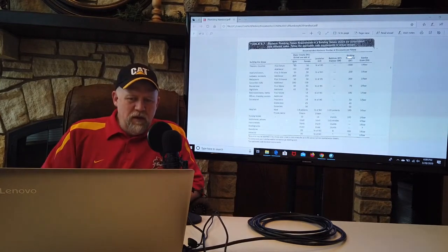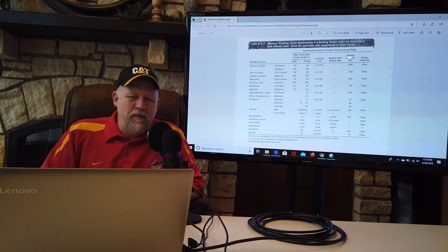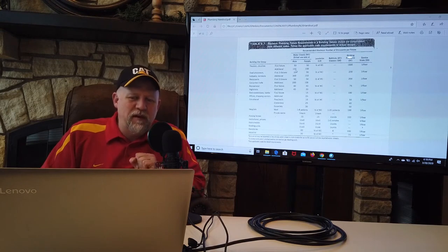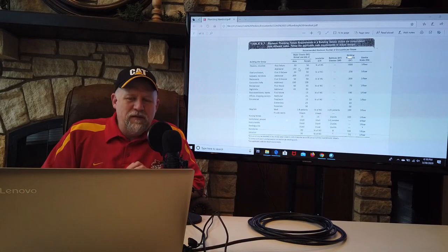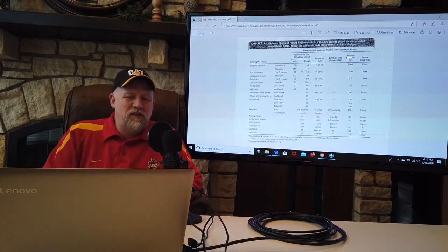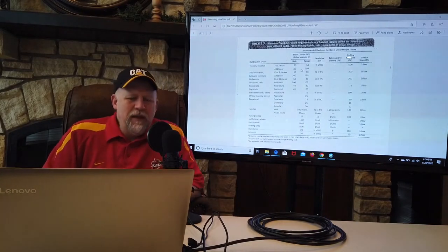Also, you do this calculation for men, and then you do this calculation for women. You have to divide them out first, and then do the 1 to 50 for the first 50, and then 150 each additional one. So then you do that after that. You do this for male, and you do this for female occupants. Always, unless you have an extenuating circumstance, you always assume a 50-50 split, male occupants and female occupants. All right, let me give you an example.